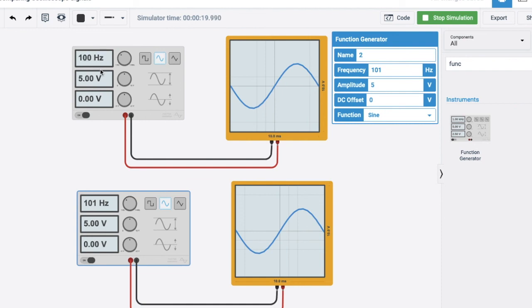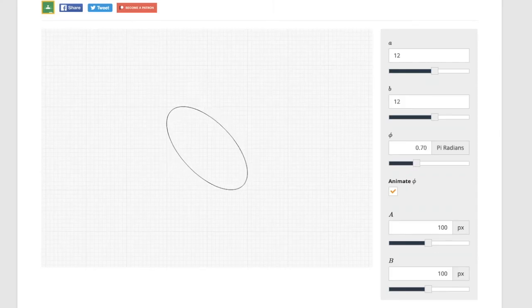But if you try to transfer one of the oscillations into the vertical axis, because apparently right now they are traveling along the horizontal axis. They exhibit the same waveform, but if I try to plot their intersection, I'll be able to display the Lissajous curve, and most oscilloscopes actually allow that kind of setup wherein you feed it with two signals and then superimpose those two signals in such a way that they vibrate perpendicularly with each other, and the oscilloscope just displays their intersection. And when you plot them over time or with respect to a varying phi, then you could actually see a dynamic pattern or a revolving pattern around a specific axis.